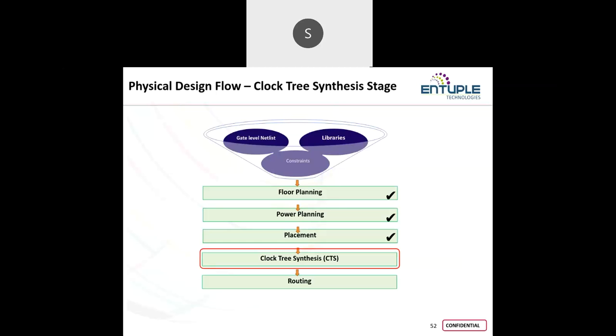When it comes to the open access database, it comes into the picture if I have designs, for example mixed signal, where I have some blocks with an analog database and some blocks with digital. At that time, I make use of the open database option. If I'm going with mixed signal, that's where it comes into the picture. Even with analog, you can see the open database options. The same way, the libraries you are using and the settings all come into the picture.